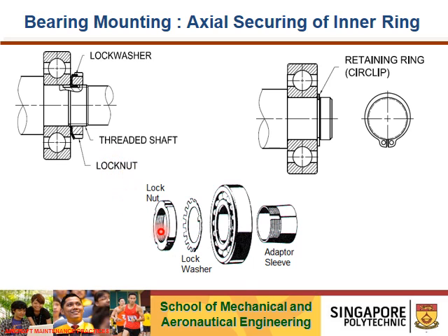So this is a typical attachment, exploded view. The bearing will be fitted onto the sleeve here. So it's a tapered sleeve. When you fit the bearing, install the lock washer and tighten the lock nut, under this type of installation most of the time the manual will ask you to set the first torque very high, maybe for example 500 inch-pound. The first torque of 500 inch-pound is to seat the bearing onto the sleeve.